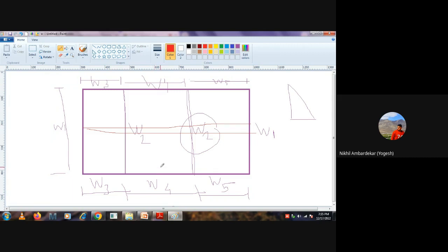So it's up to you how to simplify different wall panels. For W2, there will be triangular load outside, no? Triangular load on both sides also. Correct. But we have to consider the triangular case only once, either this one or this one. What happens if both tanks are filled? All this pressure will be cancelled because both pressures are acting against each other.